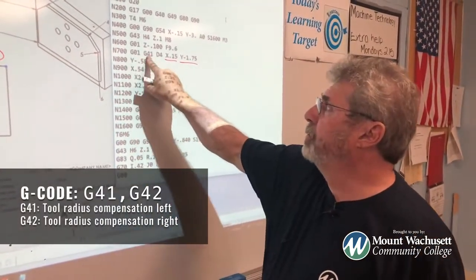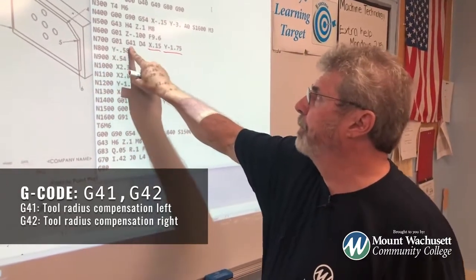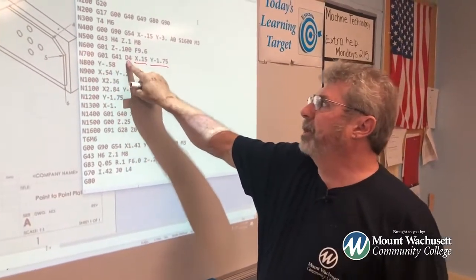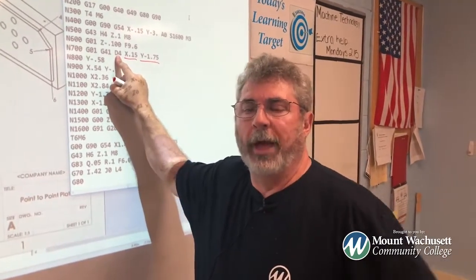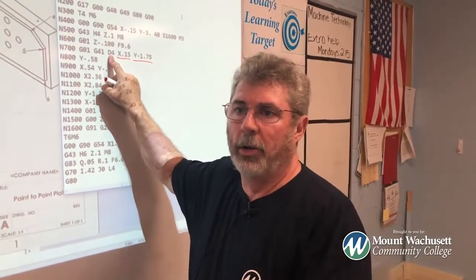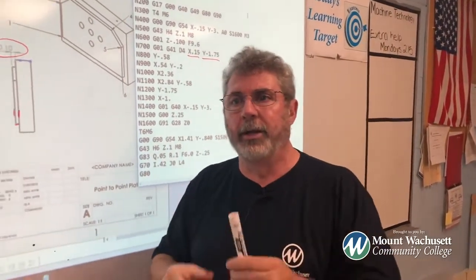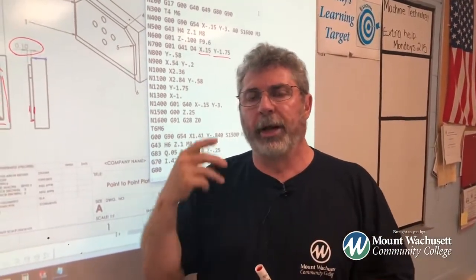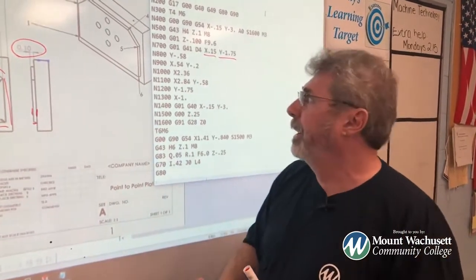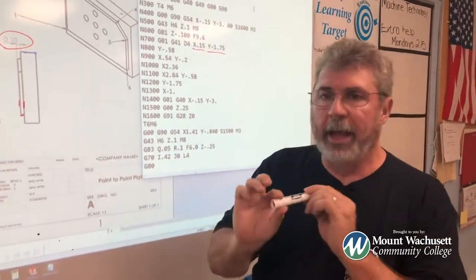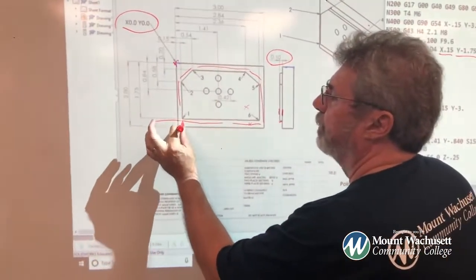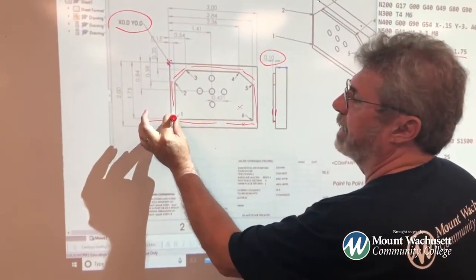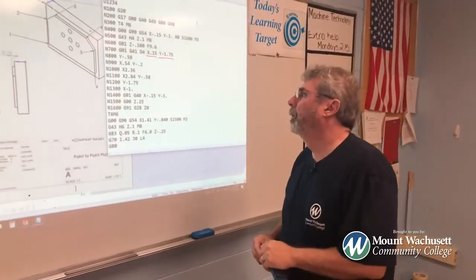So with those two G codes, you have to tell the machine, grab all the information from tool 4. That will tell you in the controller, tool 4 I have programmed for 5/8 of an inch diameter. So I told the machine I have a 5/8 cutter in that machine right now. So it's going to calculate half of 5/8, and as it's coming here, it's going to move over, so it's on the left side of that line. All right, we're rolling.